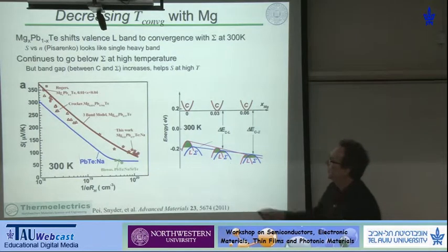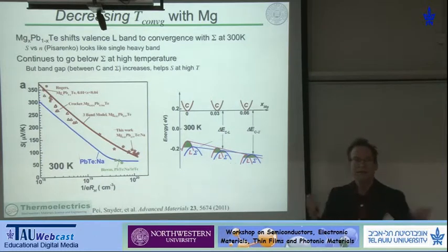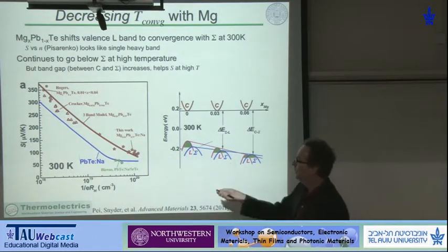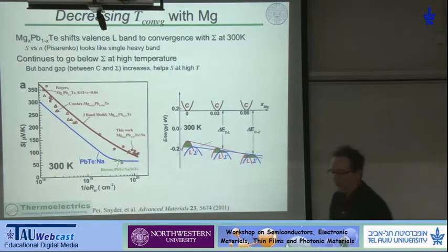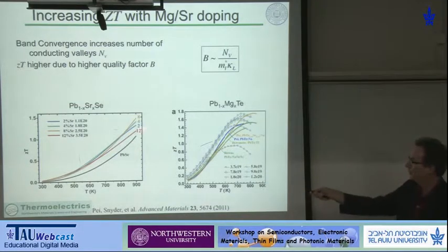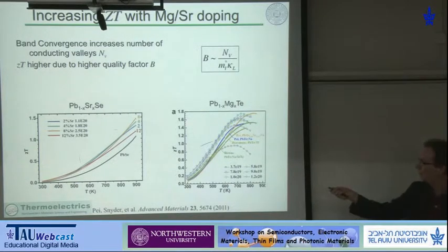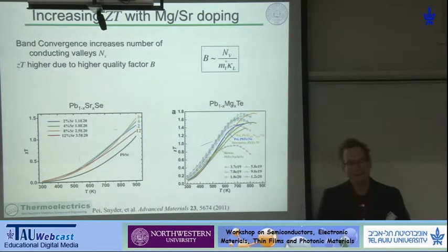What we see when we do that is the Seebeck coefficient goes up because the density of states, there's more carrier pockets contributing to the entropy, which raises the Seebeck coefficient, and that obviously helps the ZT. So we can get to now ZTs as described well above 1. We can get ZTs around 2 using these carrier pocket engineering approaches.